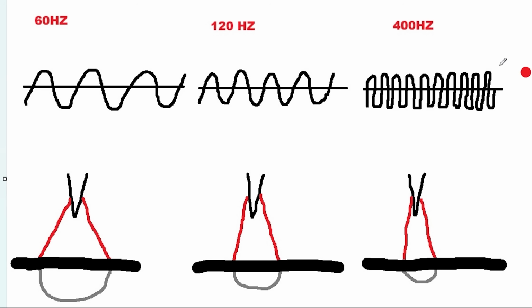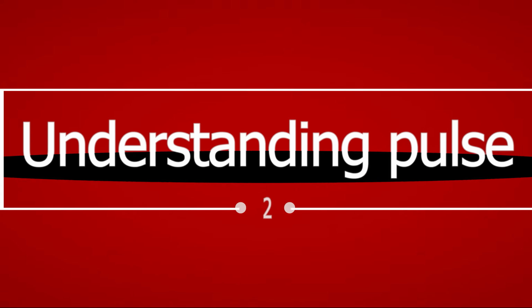Now, keep in mind, all of these frequencies here also can be done with asymmetric AC. They can be done with pulse. They can be done with different waveforms on the positive and negative, and they can also be done with different cleaning percentages or different AC balance.